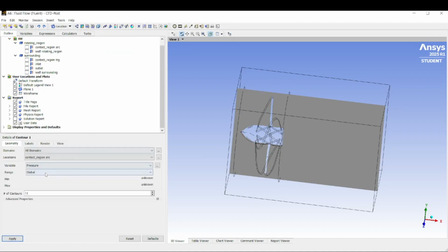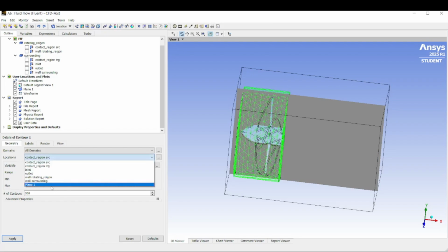To analyze airflow behavior, generate streamlines. Select From Inlet. Set the number of points to 300 to capture flow details accurately. Run the analysis to observe the final results, focusing on pressure distributions, velocity fields, and turbulence patterns around the propeller.